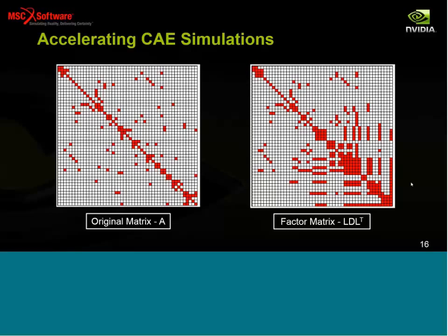The majority of the GPU acceleration that has already been performed for most structural analysis tools like MSC Nastran and Marc is with respect to the factorization of a matrix within these simulations. In any structural analysis simulation, the core component is the matrix A that represents the stiffness in the discretized model. To obtain the displacements in response to applied forces, we must factorize the matrix into one of several forms.